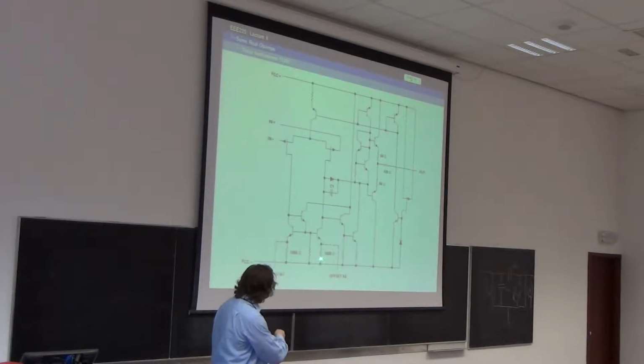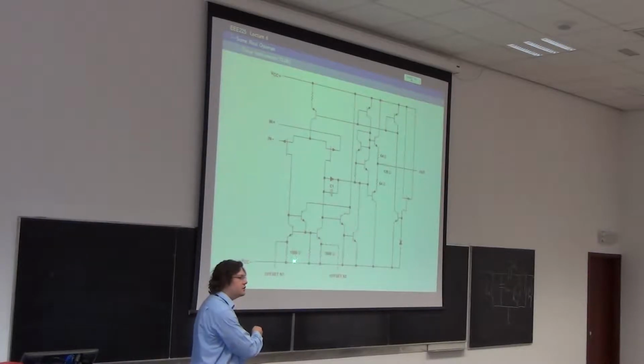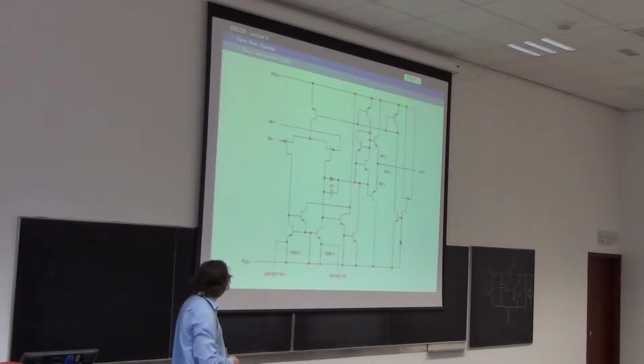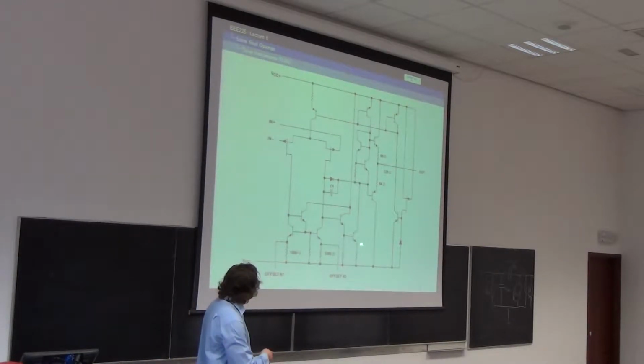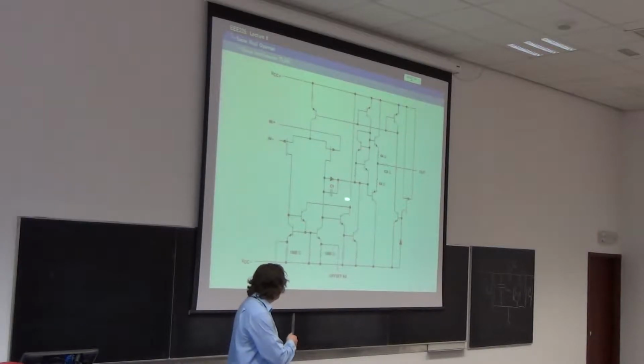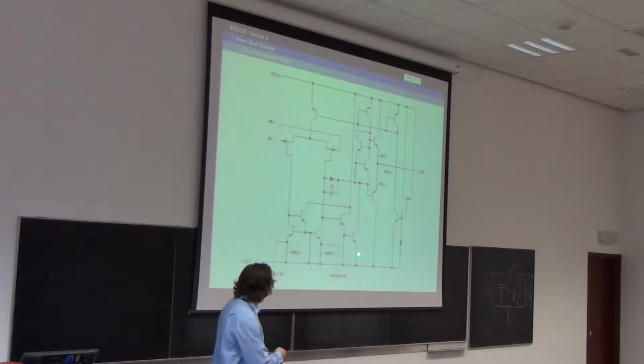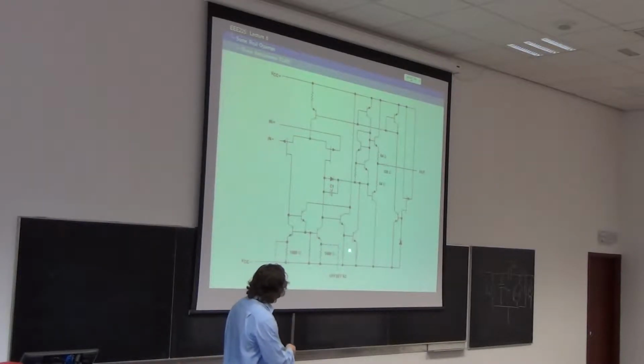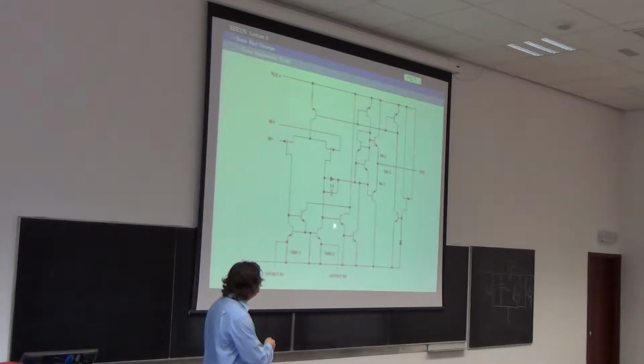And there's some degeneration in the emitters of the current mirror to try and ameliorate any slight differences between these 2 transistors. We have a Darlington pair, and there's a little degeneration of the Darlington pair, and there is this resistor. This resistor is quite significant. They will be degenerating the gain of this to set a pole in a particular place,